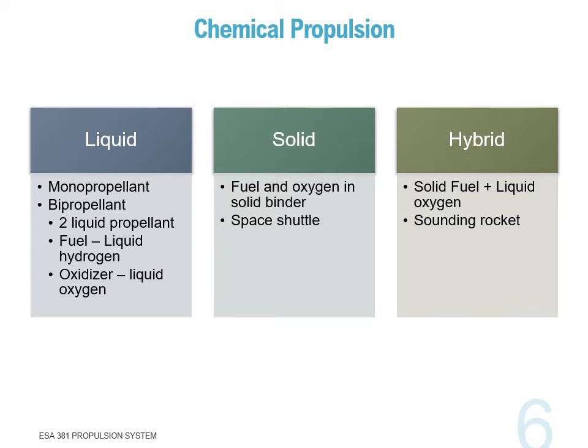Brought together under pressure in the combustion chamber by the propellant management system, the two compounds chemically react, releasing vast quantities of heat and producing combustion products. A solid rocket contains a mixture of fuel and oxidizer, along with a binder, blended in the correct proportion and solidified into a single package called a motor. A typical composite solid rocket fuel is powdered aluminium. The most commonly used solid rocket motor oxidizer is ammonium perchlorate.